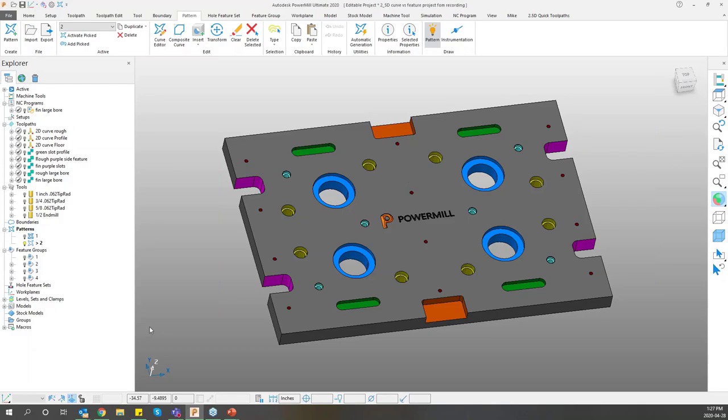This is regarding 2D. Well, of course, this whole segment is regarding 2D. Very good. Do 2D toolpaths in PowerMill show gouges and collisions like 3D toolpaths? No, not like a normal 3D toolpath, but if you notice when I went through the process, I did get the white check mark. If you're using this already, or if you start using it after this, you will notice a lot of the times you get a yellow question mark.